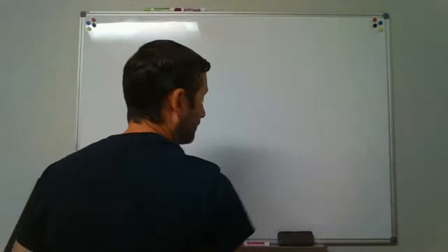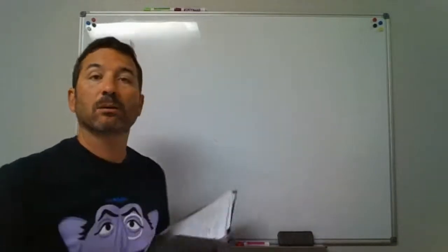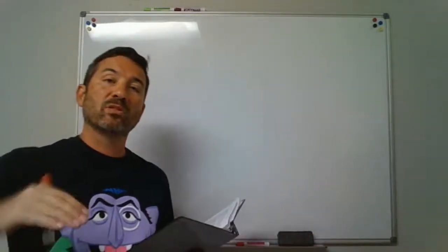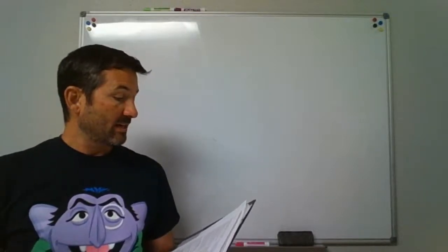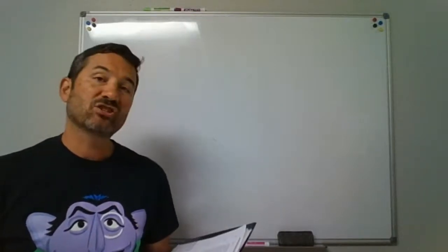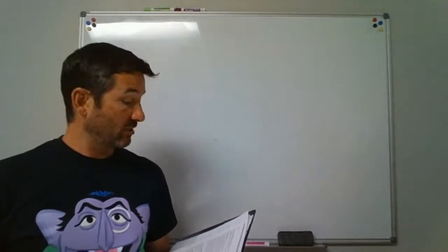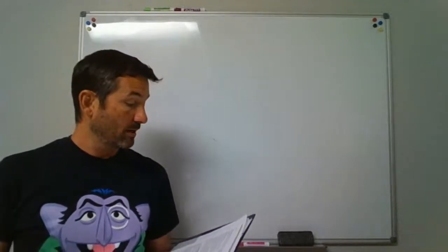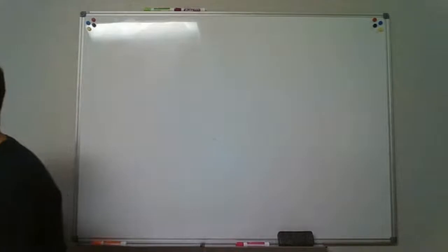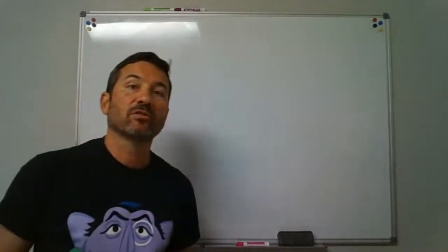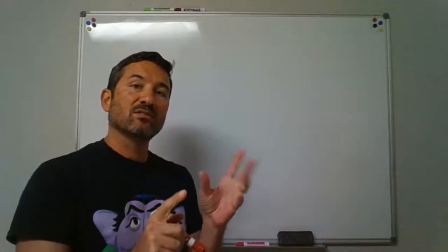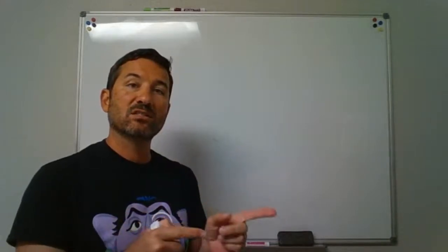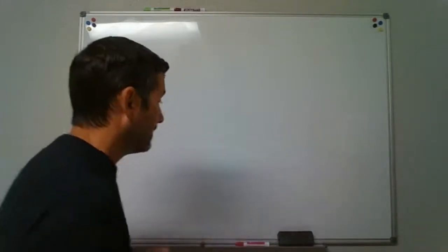Basically, it's going to be a floor level that has plumbing on it with at least 8 foot in between them. And it says if you have a drainage stack that has 5 branch intervals or more, you're going to have a vent stack. A little bit different than you just take the 2 words and swap them around, and it's 2 different things. Stack vent, vent stack. Two different things.